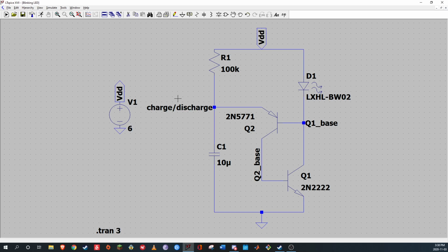Right. So normally, you'll be given an assignment, or you'll be trying to design something on your own, and you'll say, okay, I want a BJT that operates on 6 volts and can handle 500 milliamps of current, something like that. And then you would just hop on DigiKey and put those filters in. And I'll show you. I'm trying to find the name. Yeah, I've seen DigiKey, me and Jason.